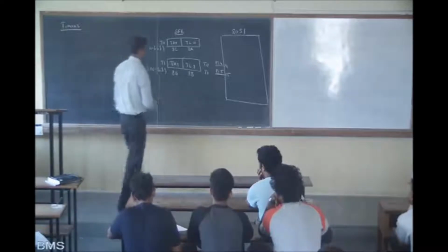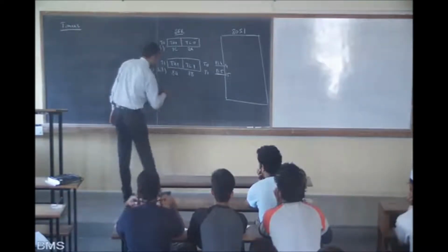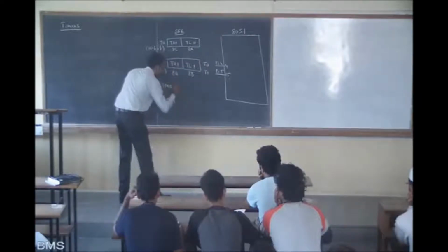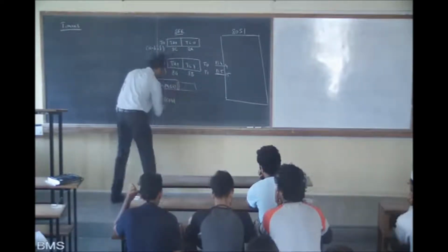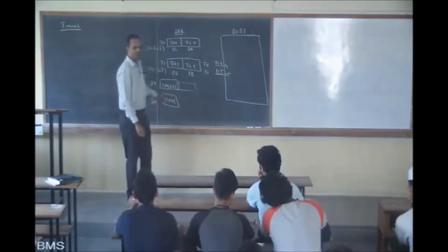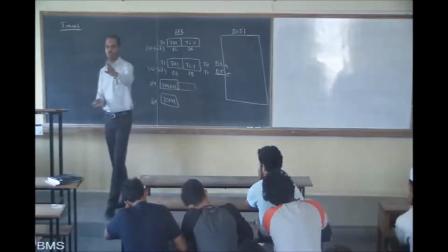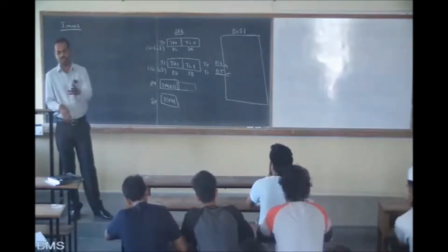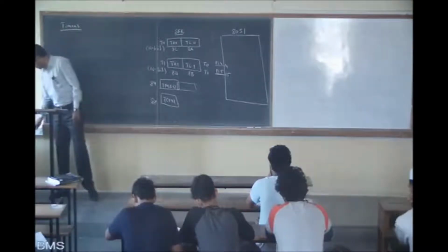How do we work with this? There are two more registers called TMOD and TCON. What is the address for these? TMOD is 89. We put TMOD in the box with address 89, and TCON is 88. These are all linked concepts. These two pins, these four registers and these two registers together form one phenomenon called the timer phenomenon. What is the timer phenomenon? It is nothing but an 8-bit or 16-bit up counter. Only up counter, you should remember; there is no down counter concept.